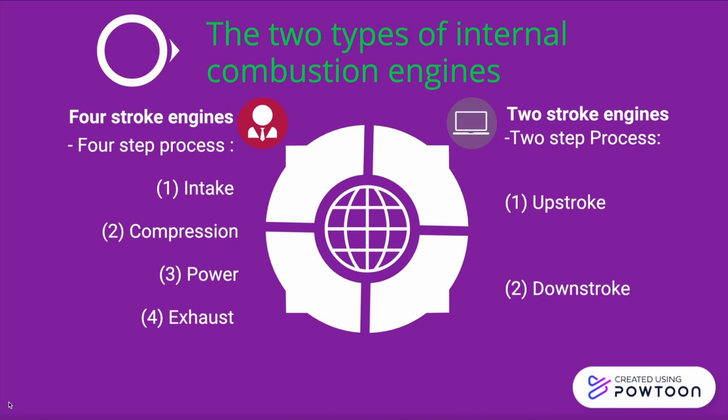The intake is when all of the fuel-air mixture is sucked into the cylinder when the inlet valve is opened. The crankshaft is pulled, and that's when the inlet valve will open and allow all of that fuel-air mixture that's needed to be put into the cylinder. This is one of the most important steps in the process.